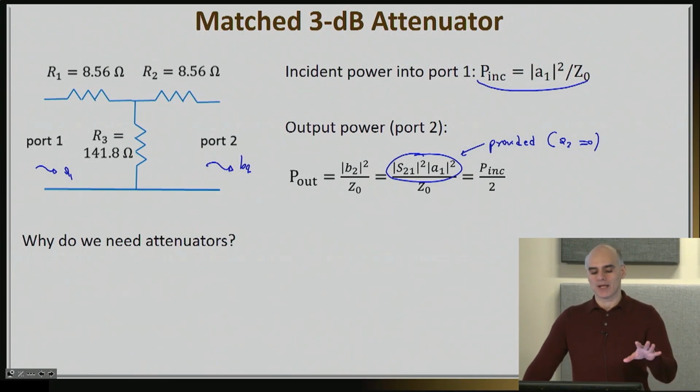For the same reason, we want matched attenuators, because once you shoot power to an attenuator, if this power might be too high and damage your device under test, you definitely don't want any of this high power to come back to you. And so having a matched 3 dB attenuator, or a matched attenuator of any type, is quite necessary to avoid any accidental damage.